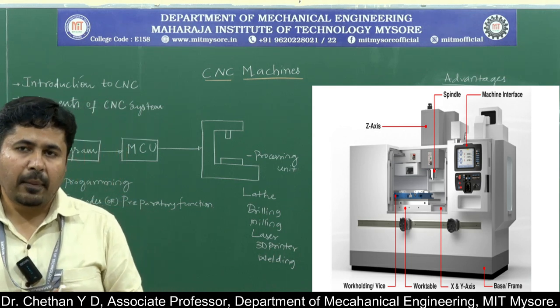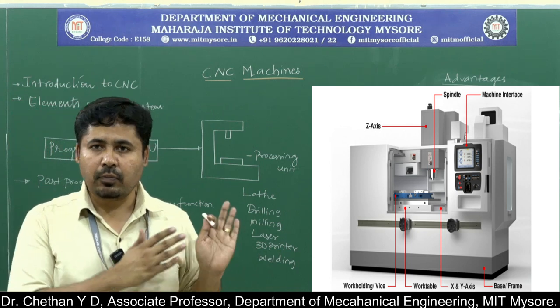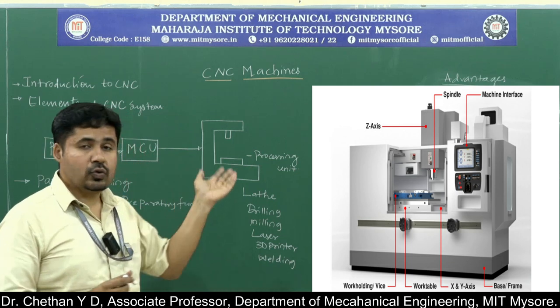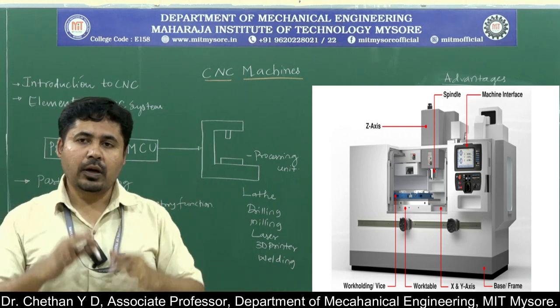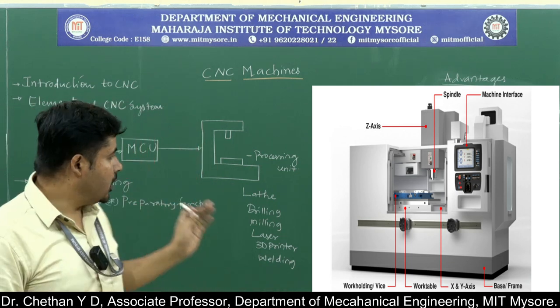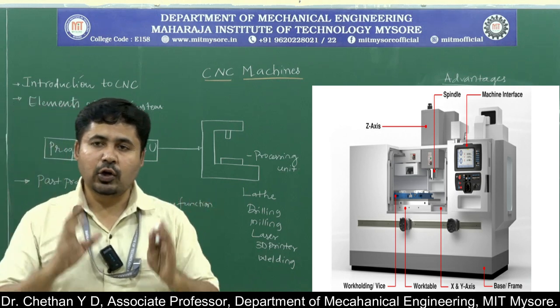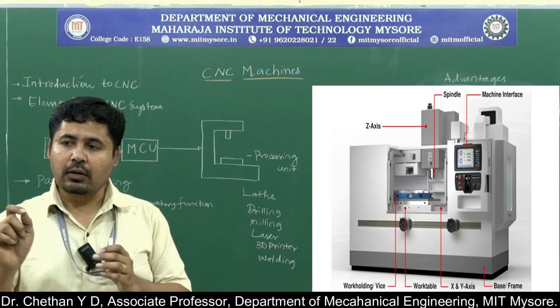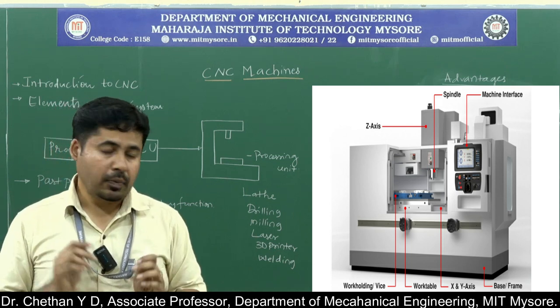These are all different metal cutting operations that can be carried out with the lathe machine. Then how do we convert that lathe into CNC? By incorporating computers, giving a set of instructions and having the control units, we can control the tool movement and get the desired shape.